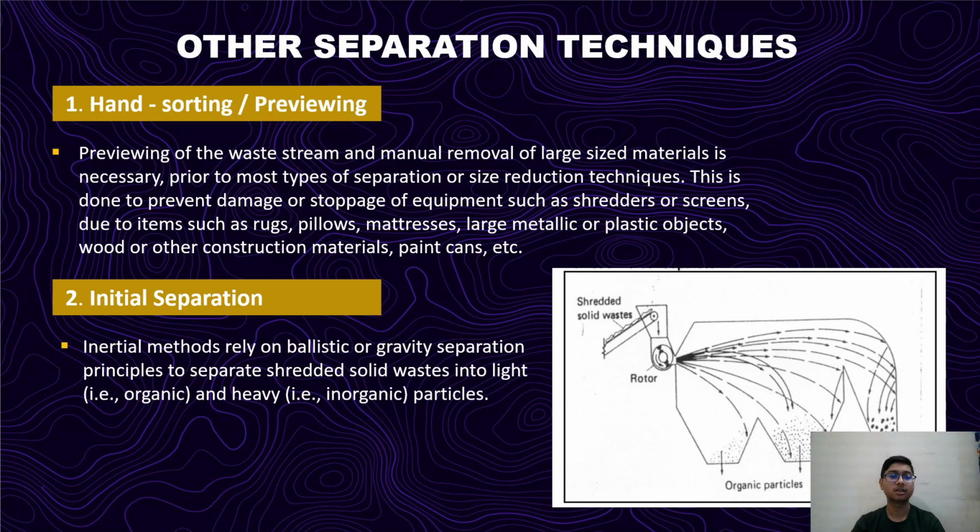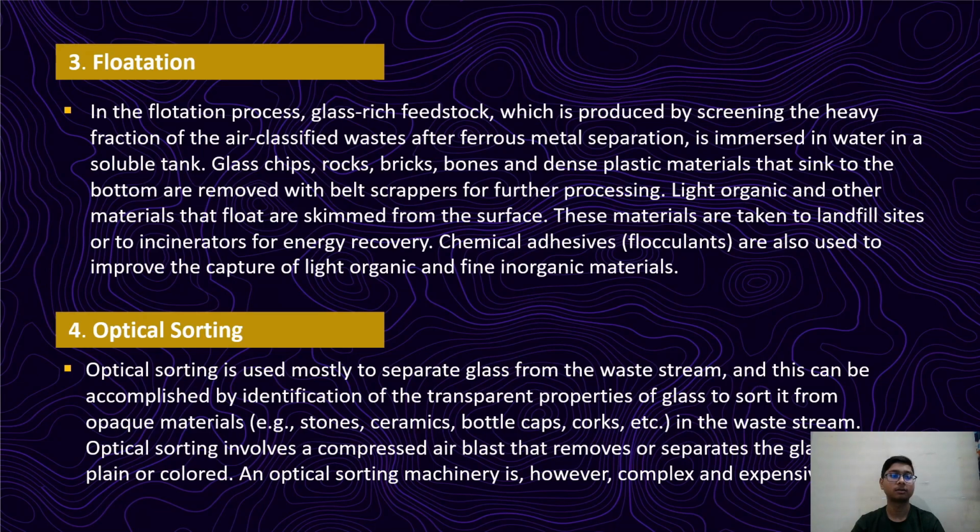Second is inertial separation. Inertial methods rely on ballistic or gravity separation principles to separate shredded solid waste into light and heavy particles. Third one is flotation.